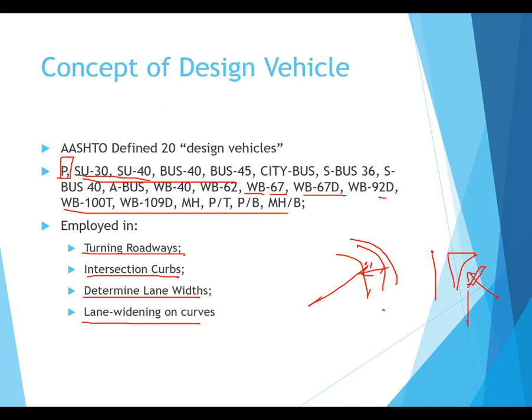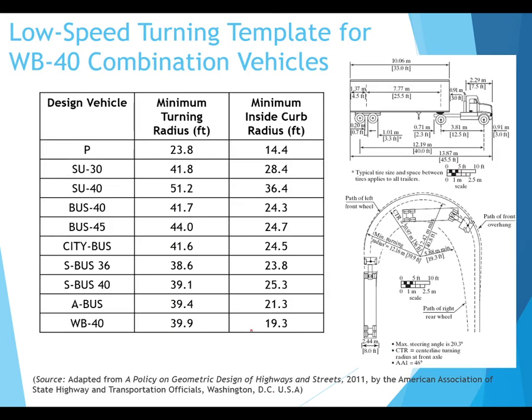We want to know the regular lane width, and we have here between 10 to 12 feet. We also try to figure out what is the width of the biggest vehicle on the road. And also, when we do lane widening, at any turning, we don't keep the 12 or 11 feet, we go up to sometimes 20 feet. Why? I'm going to show you when we talk about simulation of this design vehicle. I think it's the next slide here. Yeah, so this is an example for this.